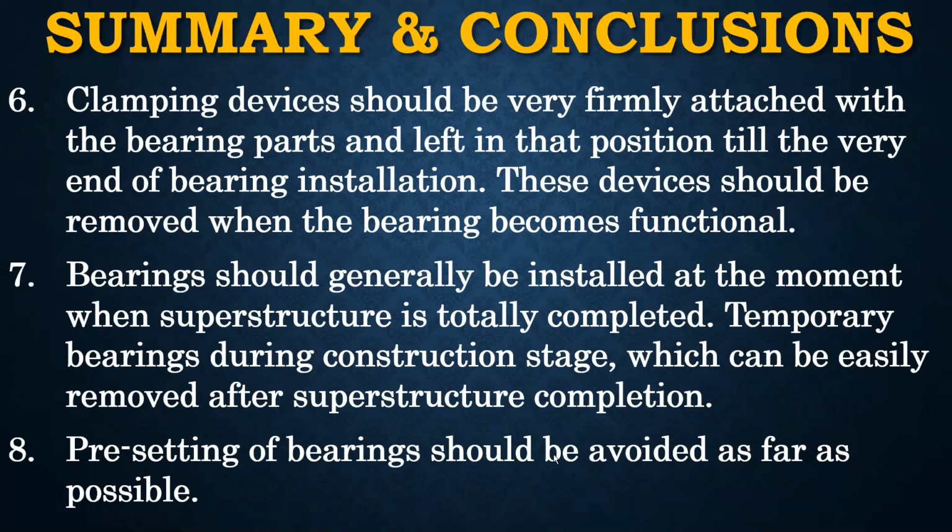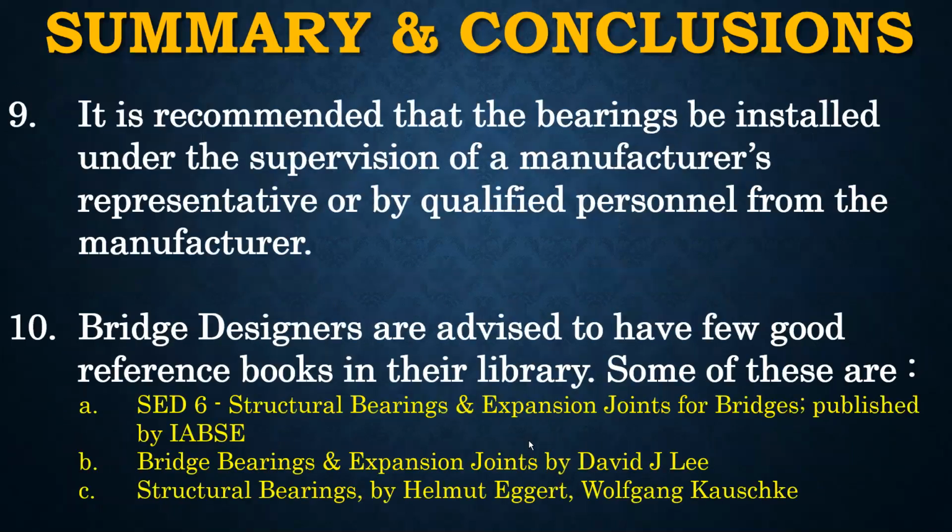Bearings should generally be installed at the moment when the superstructure is totally completed. Temporary bearings during the construction stage, which can be easily removed after superstructure completion, should be followed. Pre-setting of bearings should be avoided as far as possible. It is recommended that bearings be installed under the supervision of the manufacturer's representative or by qualified personnel from the manufacturer.